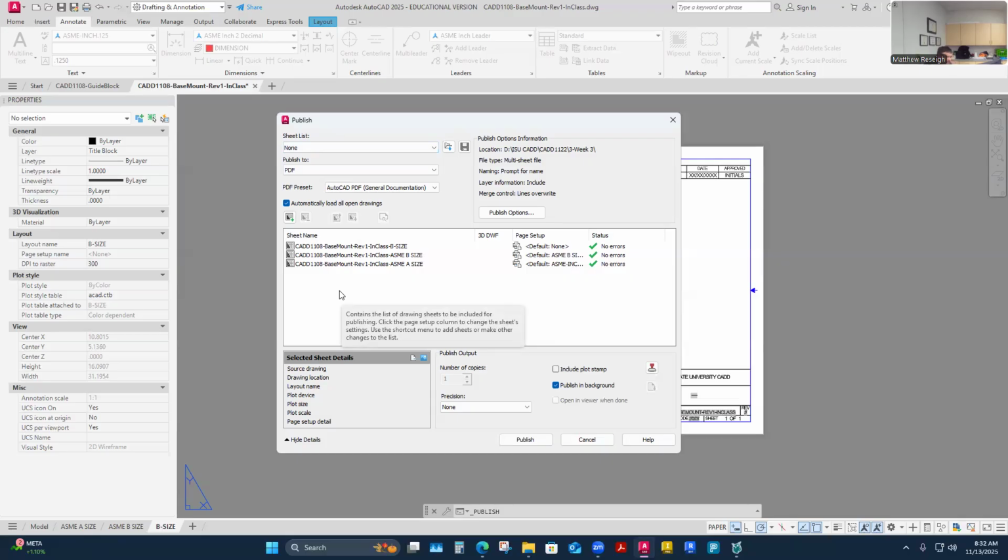I would say it's more common that when you do revisions, you actually revise the whole packet. New revision labels go on the sheets that have revisions associated with them. The master list, probably at the front of the sheet set, is going to carry all of the revisions through it. And then each sheet will just carry the revision history of what happened to that particular sheet. So it's pretty common that I've got all my sheets as part of my revision process.